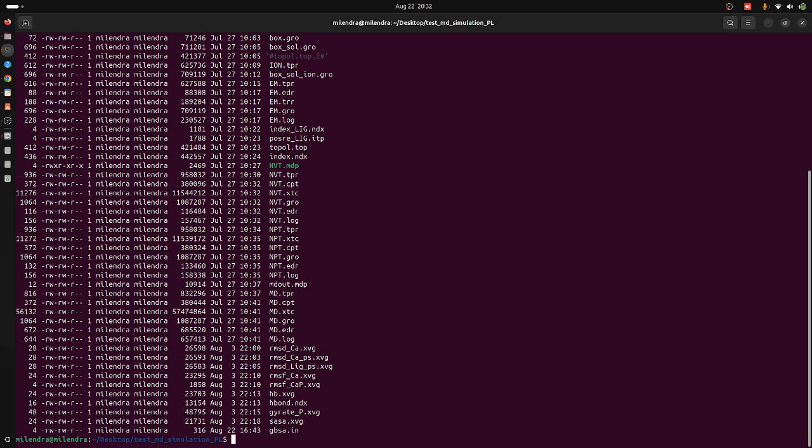So we just need some input files, right? And we have already all the input files, like we need the md.xtc GROMACS file, the tpr file, and the index file, right? And most important is the parameters file, like what parameters we are using, and how many frames we consider for the calculation, right?